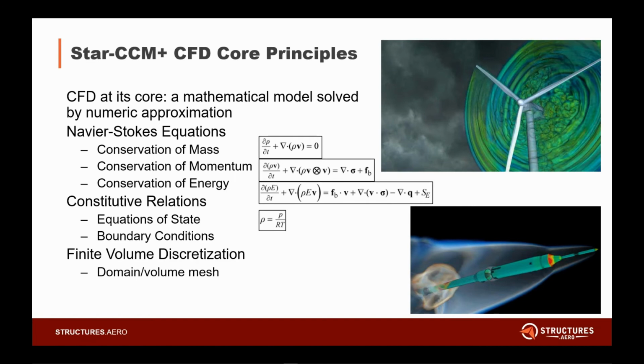So for CFD, it's really the Navier-Stokes equations that you're solving: conservation of mass, momentum, and energy. These are partial differential equations, and you have a larger number of unknown quantities than equations. So there's a couple of constitutive relations and models that you add in to help provide closure to the mathematical model.